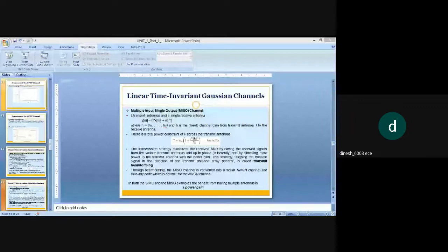So the coding independently varies over each of the subcarriers. You can see for each subcarrier, the architecture with appropriate power and rate allocations achieves the capacity of the frequency selective fading channel. So the coding across subcarriers cannot improve the reliable rate of communication, but it can still improve the error probability for a given data rate.